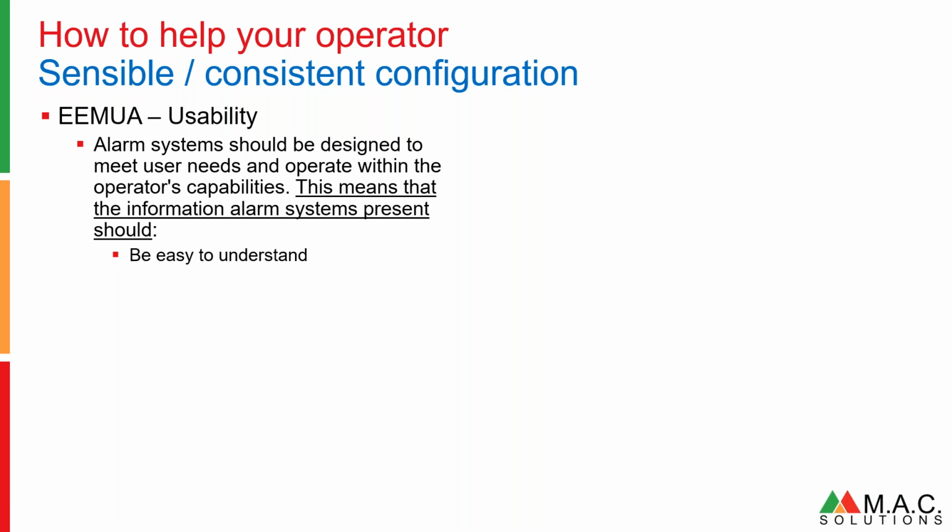A system I did in a power station in Ireland, I won't say north or south, the alarms for a low flow alarm or a low pressure alarm, the low actually said not high. It was an Italian system, they'd configured it's not high, it's low. So when the alarm was normal, the actual alarm message said not high. Not high was low, i.e. it's low, it's not high. When it went normal, it said it's not high.